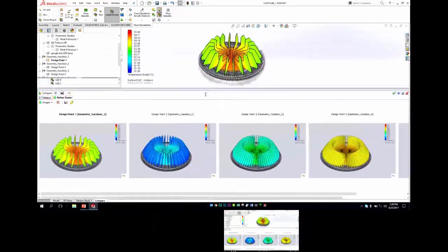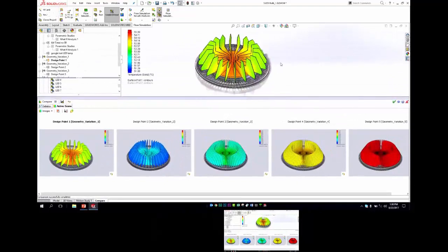So one very interesting result here, and it's definitely a counterintuitive result. So we basically found that more fins are not necessarily the best. In fact, as you get beyond 40 fins, you're really starting to restrict airflow. So if the viscosity of your fluid was different, well, maybe we'd get a different result. But the viscosity of air suggests, in this case, that we can see pretty clearly that 40 fins is better than 20 fins, but it's also better than 60, 80, and 100.